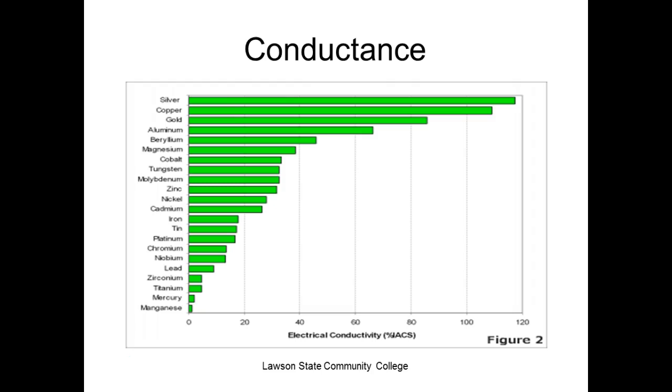So silver, we use that as a plating, especially on what we call contacts. Contacts is a method that we use to make and break circuits. So basically, if you was to look inside a light switch, you see it's just got two things, and they just touch together. When they touch together, it makes the circuit and allows current to flow, and then you flip the switch in the other direction, it does what? Well, right there where those two wires come together, that's a potential for a higher resistance, right? You understand? And anytime I put current through resistance, what happens?